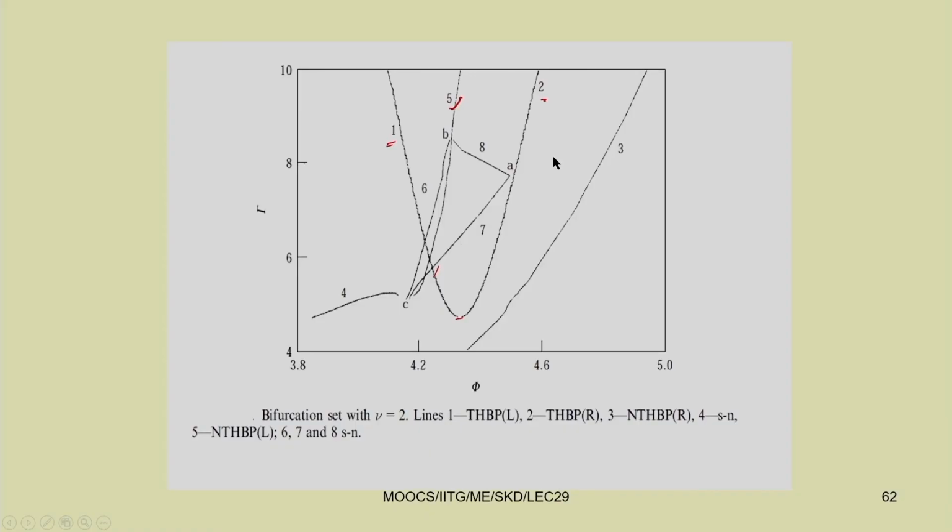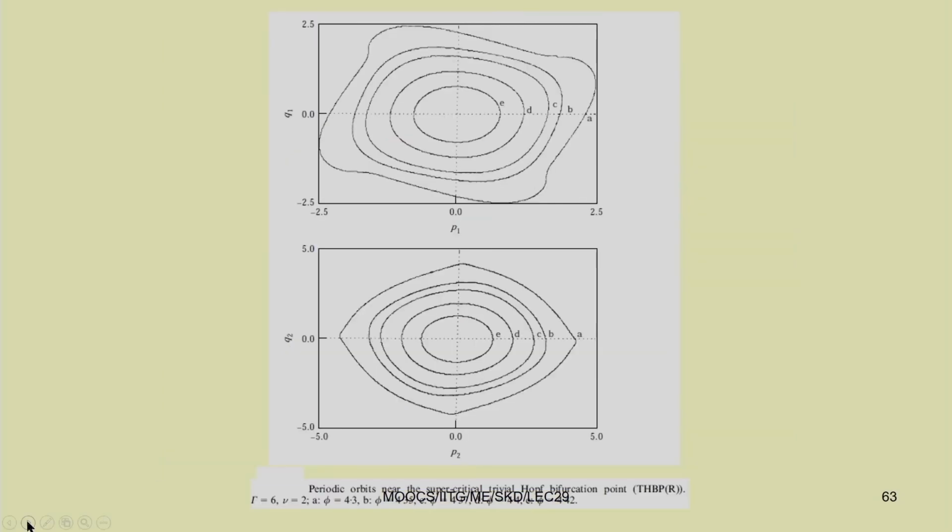This is a very critical system. Though the system is very simple, that is, a simple cantilever beam with an attached mass excited at its base with a harmonic force, the system yields a number of bifurcation points. In addition to the fixed point response, we can see periodic, quasi-periodic and chaotic responses. Near this Hopf bifurcation point, the trivial state Hopf bifurcation point, by changing different values of phi, we can get different periodic responses.